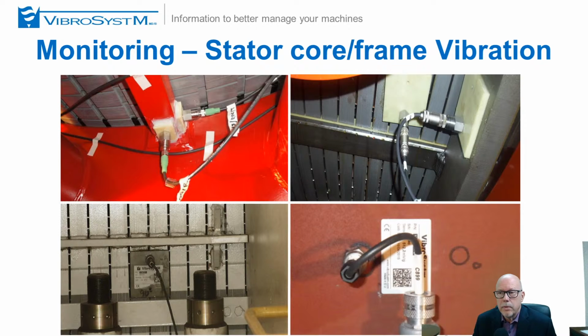Your core might be out of order or might fail completely in a very short period. So we've had a few cases where this was an issue, and one of the things we did was to install piezoelectric sensors. In this case that is sufficient because there's no high voltage here. And we monitor closely the core and the frame to see if there's any discrepancy. We do it on hydro generators as well. We do it on SAG mills and ball mills. And the idea is to make sure that the structure is sound and everything is working properly.